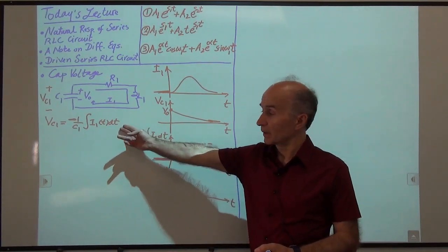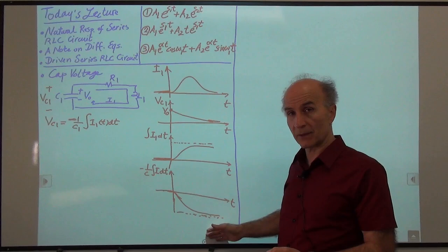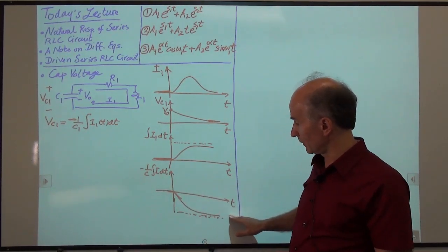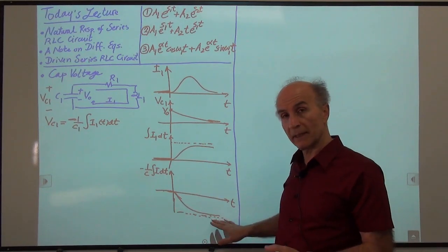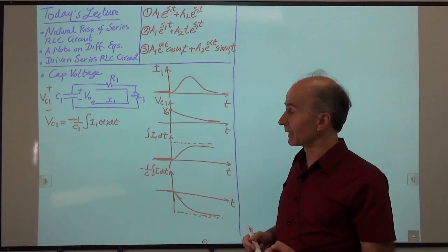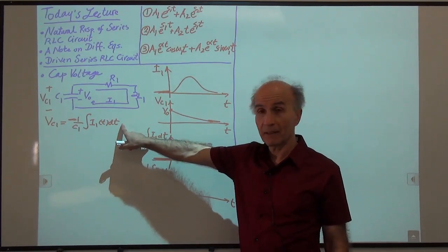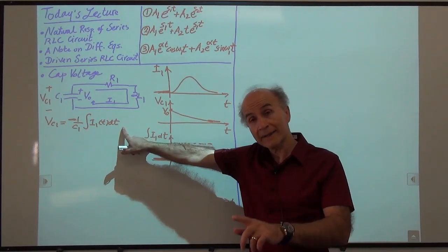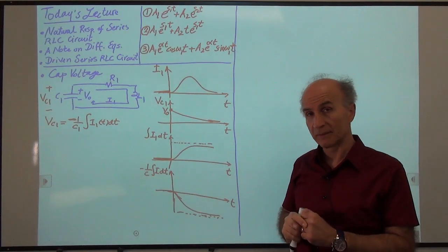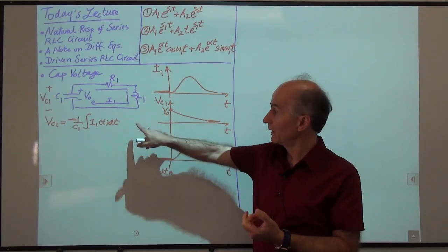What's wrong with this integral that gave us a different answer? This doesn't look correct, right? The voltage on the capacitor should eventually go to 0, not to some constant negative value. All right, well, what we have done wrong is that whenever we integrate, we have to remember about the constant of integration. The constant of integration is not always 0. So we can add that here.